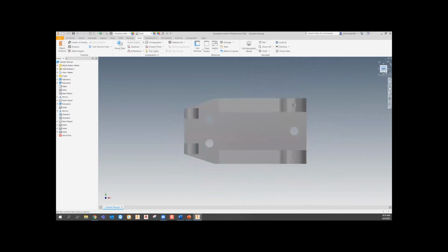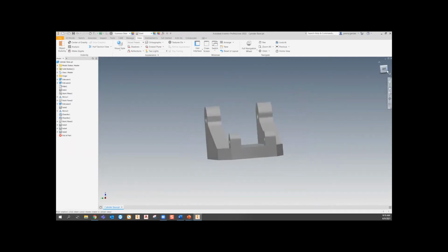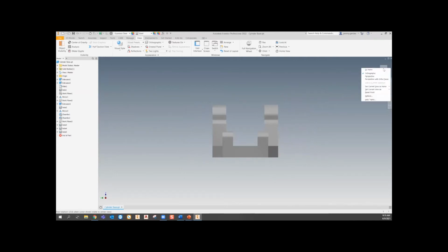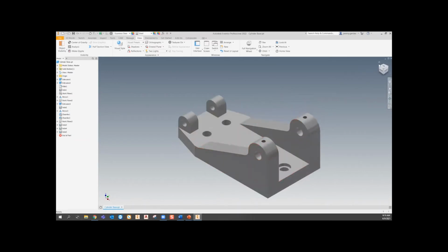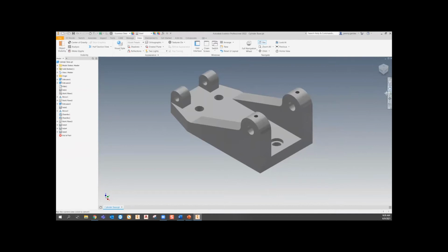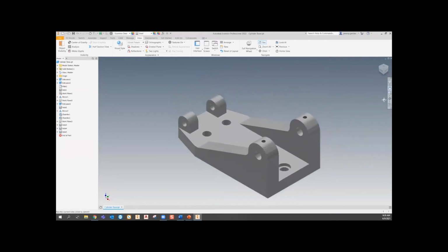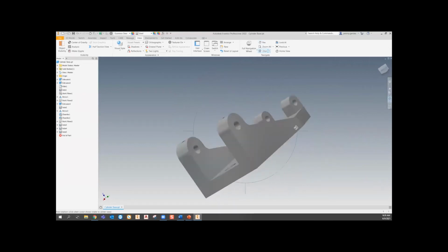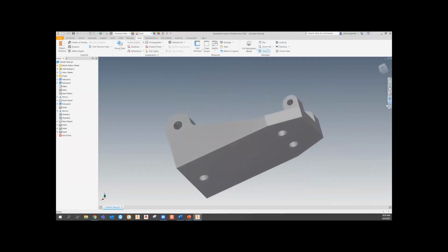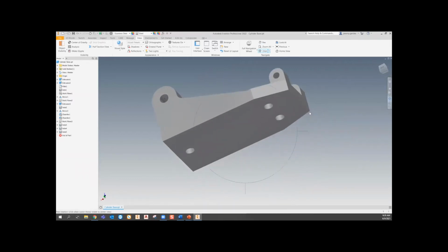And this, where it says top here, if you draw the model and go, okay, that's not going to be my top. I know my top will just say, I want it to be that. If you right click, you can set current view as top. And you can change all that. Then you can show the home view. And you can change that. You can pan. You can do a zoom all. Do a rotate. It'll spin on a center axis. And then the look at, I'll show you that.